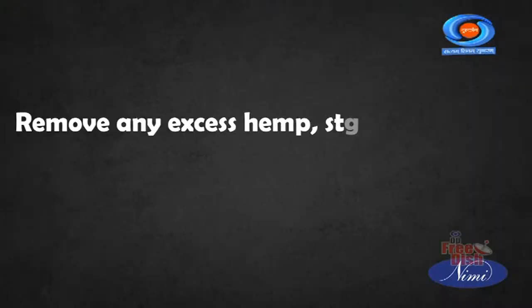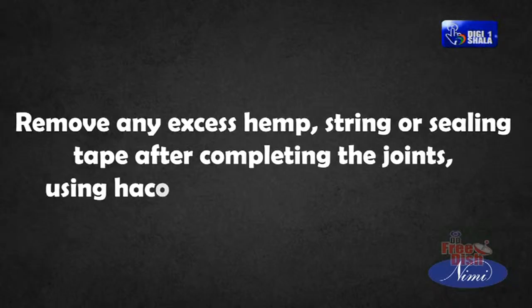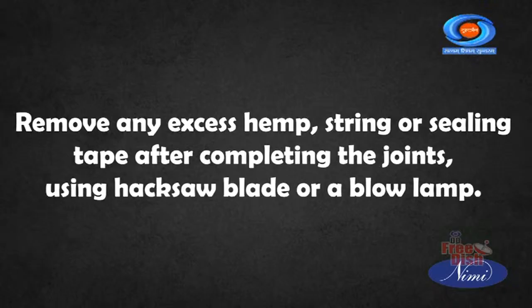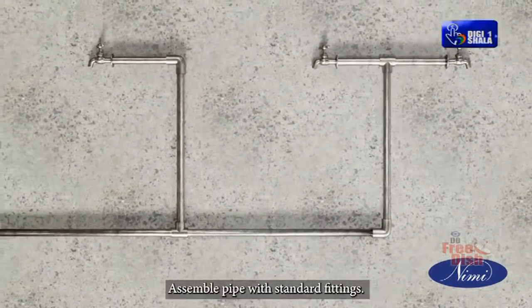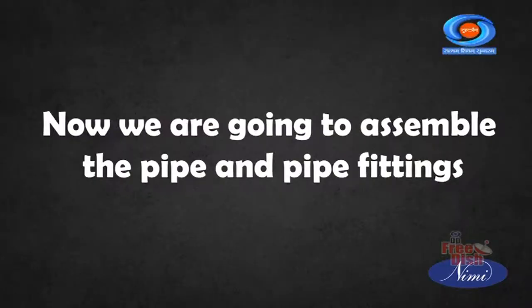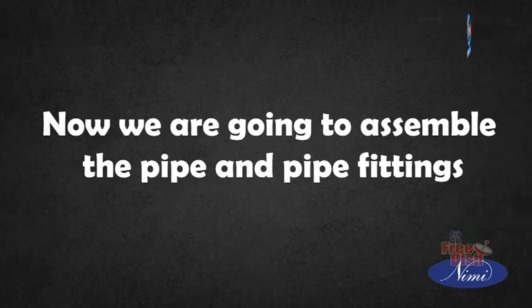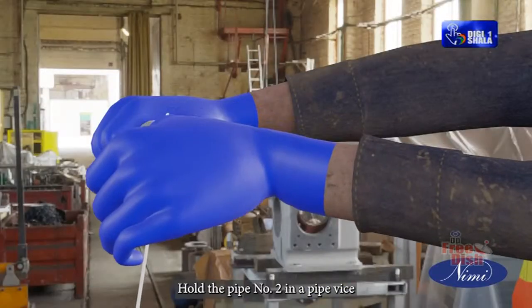Remove any excess hemp, string or sealing tape after completing the joints using a hacksaw blade or a blow lamp. Assemble pipe with standard fittings. Now we are going to assemble the pipe and pipe fittings. Hold pipe number 2 in a pipe vise.